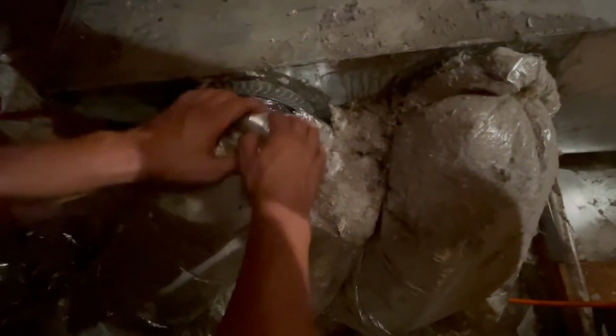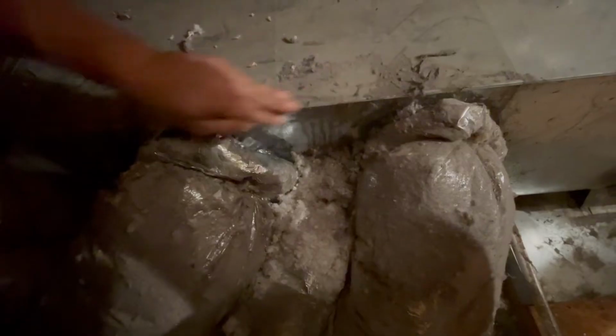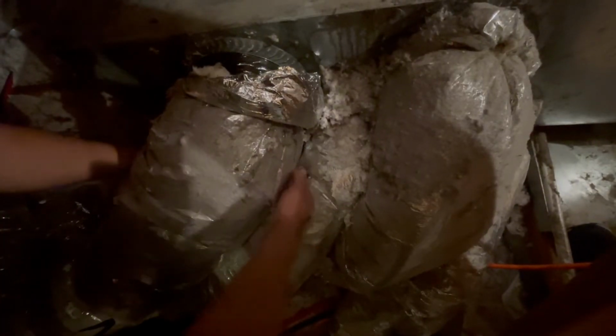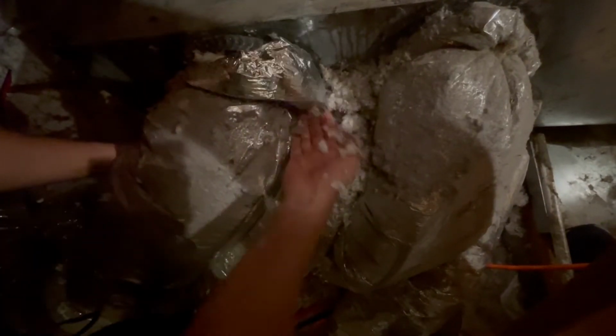A couple things I see right out the gate. I've got some exposed ductwork right there that's going to cause some condensation issues. This entire seam right here could result in air leakage, but something else I'd like to point out, Dustin, when these ducts are touching on the plenum like that, that's just going to make them sweat. Correct. If I run my hand right here, soaking wet.